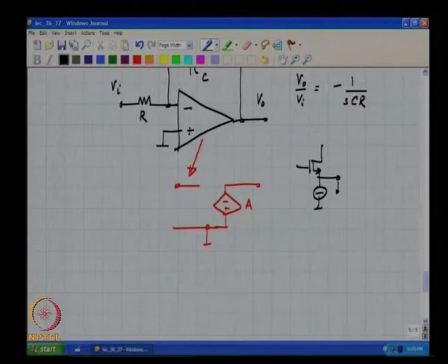But on the upper side you will be constrained, because of the transistor driving this, which is most likely a PMOS device, and this can go one overdrive below supply, which means that this voltage can go only 2 overdrives plus a VT below supply.